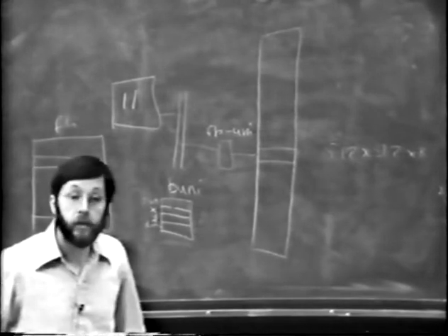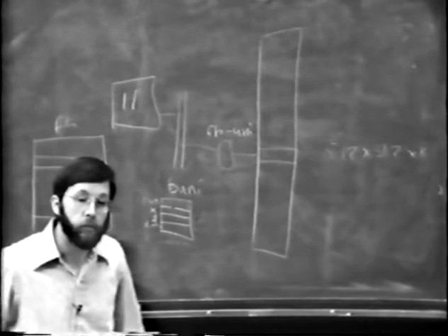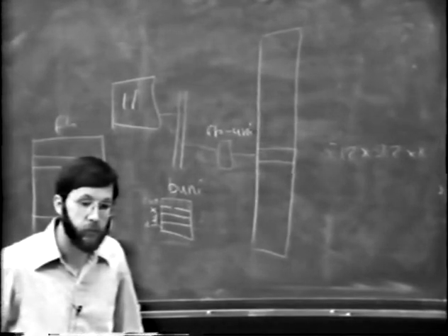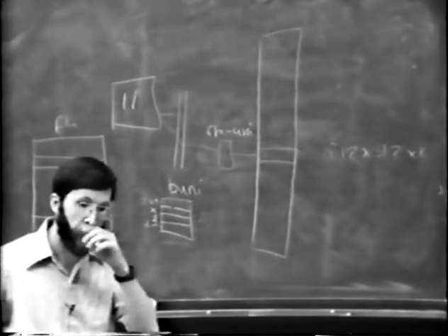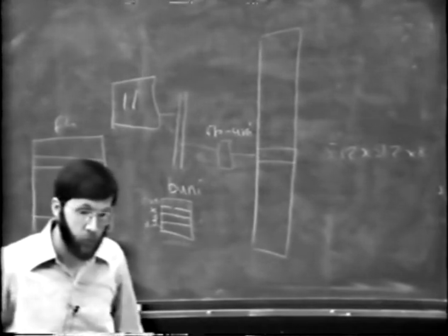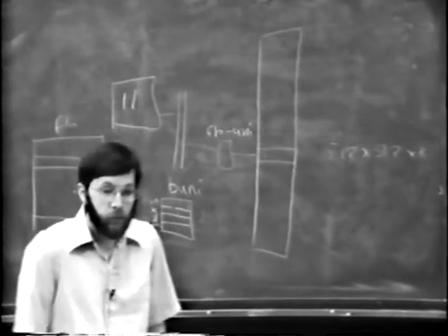Go ahead. Question about yet another technique. Now that we have single processor chips with 32-bit addresses, or at least 24 bits at the moment, what about a scheme in which you simply put the bitmap directly in the memory, inside the user space, and you could use the auto-increment and auto-decrement modes of the processor to go through, or use a block move to simulate DMA, or whichever.